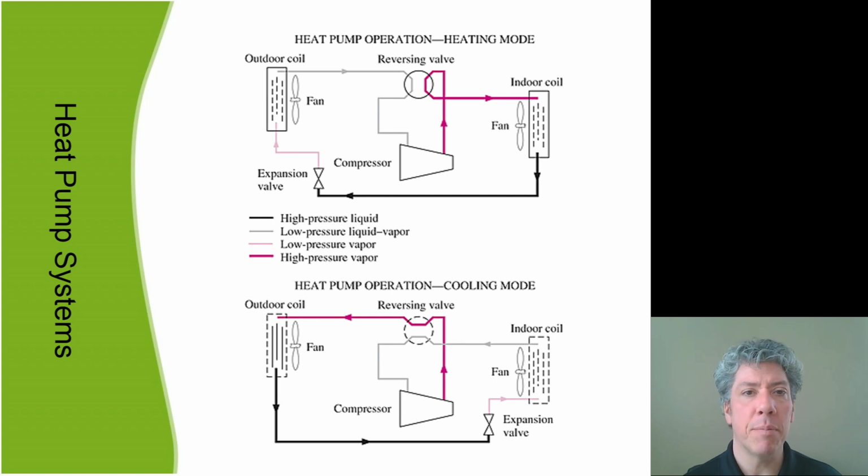That's really the problem with heat pumps, because when you really want the thing to work is when it's really cold outside, and partially because of the water vapor freezing on the outdoor coil and having to be defrosted off, but also partially because you're trying to pump thermal energy from a cooler source. Because of those reasons, the heat pump is less efficient. And you're not going to solve the fact that it's harder to raise thermal energy from a lower temperature to a higher. That's just the nature of the beast. But if you could solve the problem of water freezing on the outdoor coil, like I said, you'd be quite wealthy.